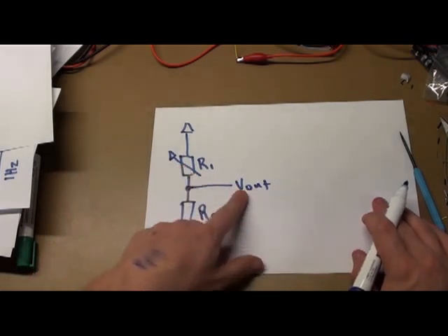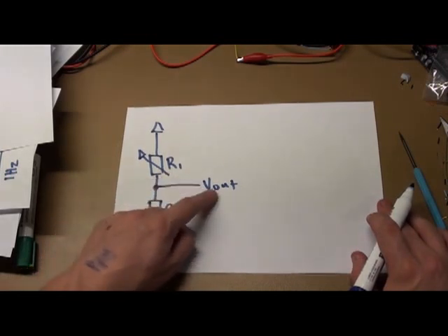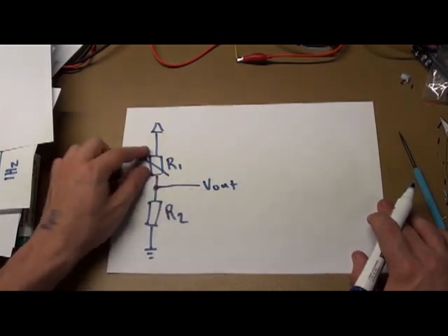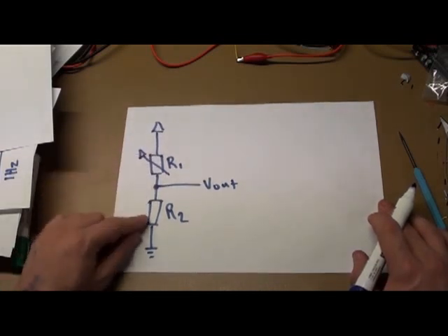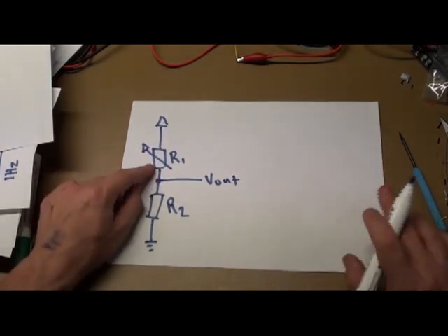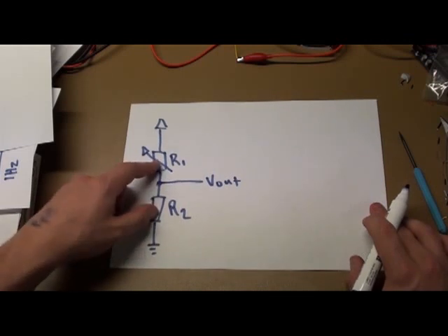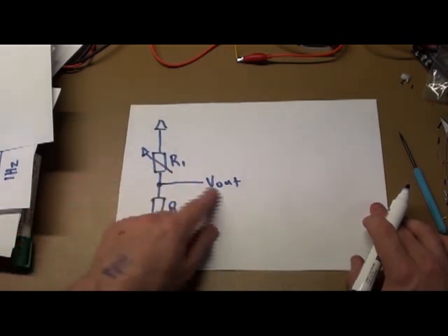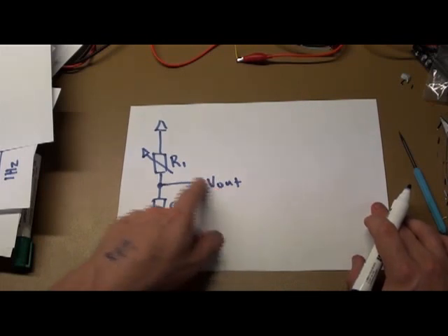And you'd be right, but the problem is noise. So this strain gauge does not change its resistance very much. So this might be 120 ohms and this might be 119.998 ohms. Now if you were to put that in your resistor divider formula, you would find out the V out is very, very, very, very small.